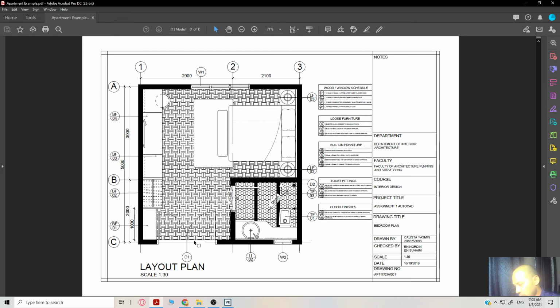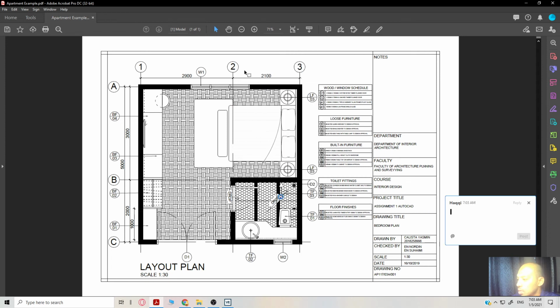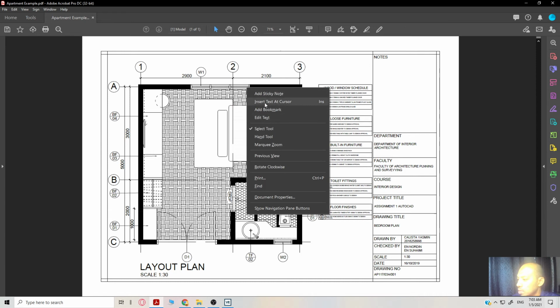And as for the windows, you have a 3-bay window here, which I think is 600 per bay or per casement, so 600 times 3, that's going to be 1800 millimeters in terms of the width. The height, I think let's put in 1200. Here let me just key in, insert text here, so it's going to be easier for you to refer later.